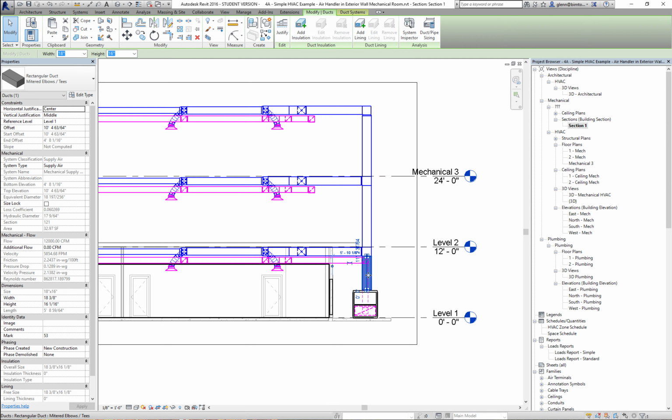Or even what they did here in Y2E2, which is another valid way to do it. Yeah, our building's kind of strange. You can think about all our atriums as being different zones: the red zone, the blue zone, the yellow zone, and the green zone. There are different air handlers on the roof that handle different subsections of the building vertically. Since it's all up on the roof, they didn't have the ability to put them in the middle somewhere. They split it across the roof, so they have the north end and the south end. Okay, which is often a reasonable strategy. Let's talk about that.